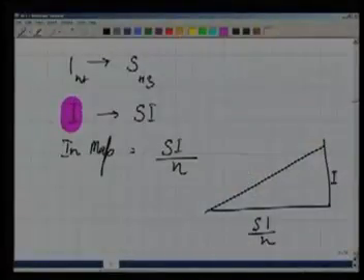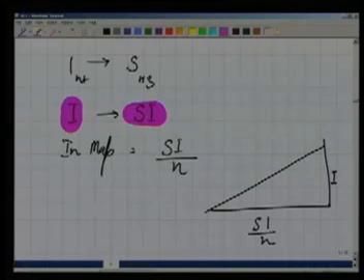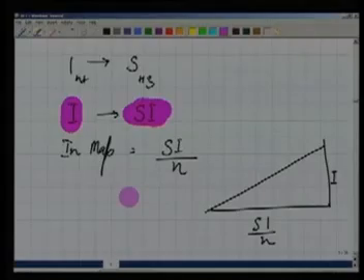So how much horizontal distance should we travel? This horizontal distance we will try to find using the slope. Let us look at that. Corresponding to a difference in height I, if the slope is 1:s, the horizontal distance is s into I. So on the actual ground, we need to move by a horizontal distance of s into I in order to go up by I, and if we do so, we are following that contour gradient.